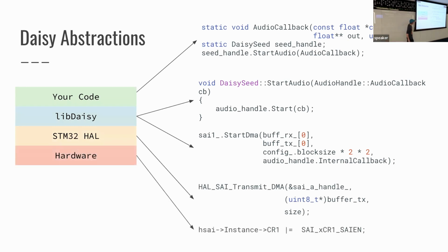And this is the part, the reason I have this slide, that is different from native programming a lot. This is where you actually have a memory-mapped register for the SAI, which is a serial audio interface. You're writing to control register 1, you're writing this enablement here. And that's actually what makes it bare metal: interacting with a physical device directly in your code.